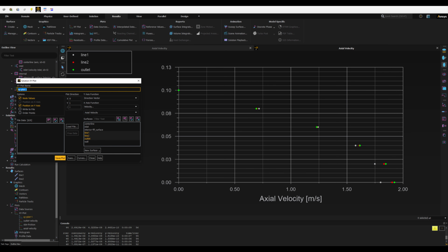I can change this name to axial velocity, all lines. Save it again. So this profile downstream is fairly close to the fully developed profile at the outlet. If you redo this plot using the fine grid result in the next step, you will see that this is not actually the case. The coarse grid used here doesn't capture the boundary layer development properly and underpredicts the development